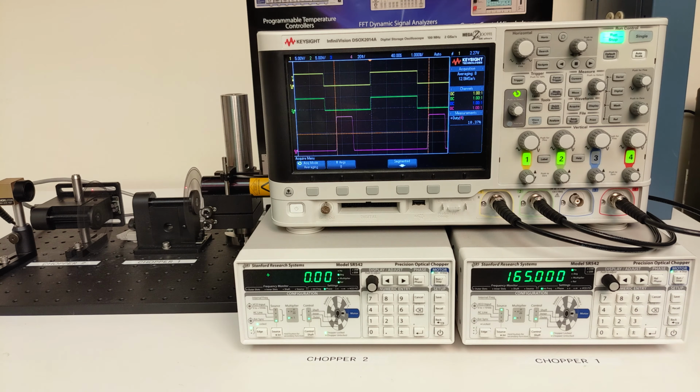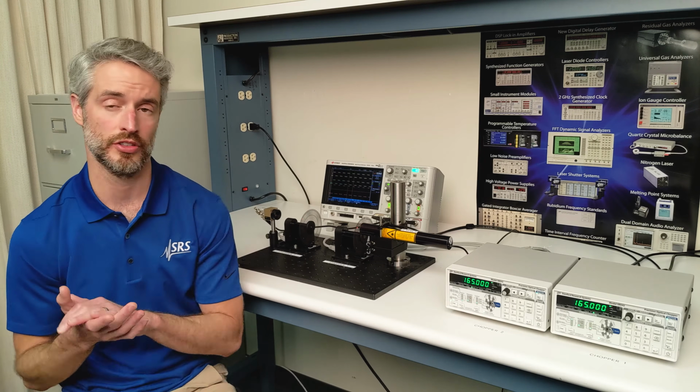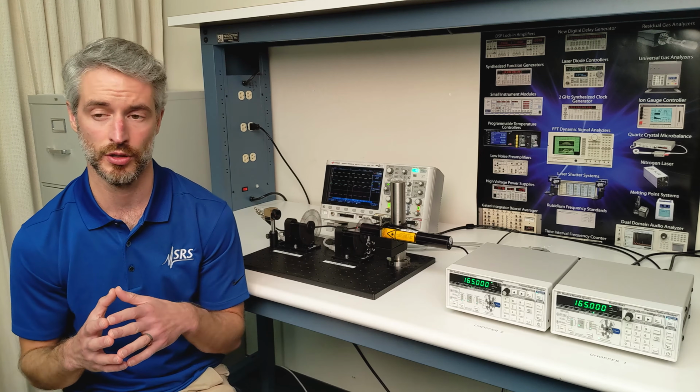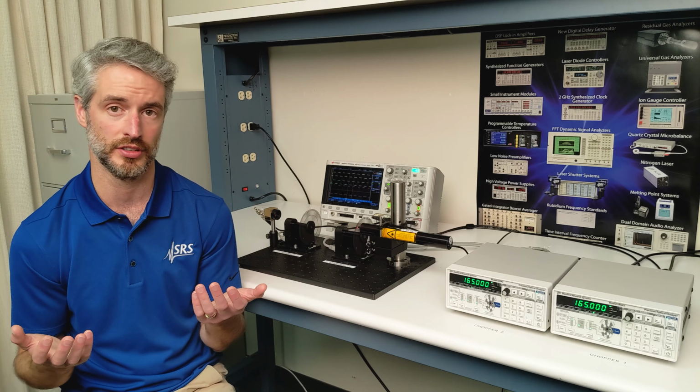Similarly, any lateral or vertical displacements of the photo interrupters on each chopper head will shift the reference outputs, due to minute manufacturing and assembly variation, for example. So reliance on edge alignment of the reference output signals alone is never as accurate as direct measurement of the photodiode output. If your signal to noise is weak, you may not be able to visualize the chopped waveform directly on an oscilloscope. In that case, you may be using a lock-in amplifier to recover your signal.